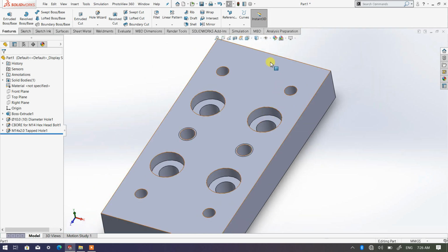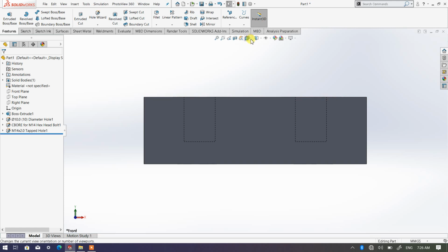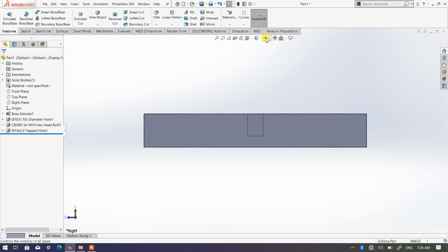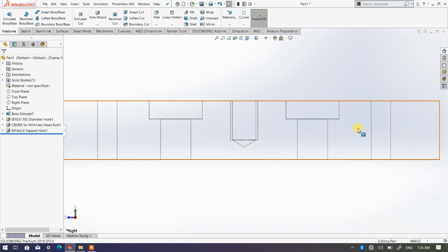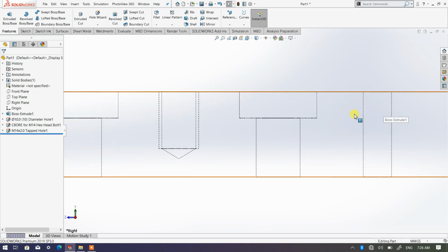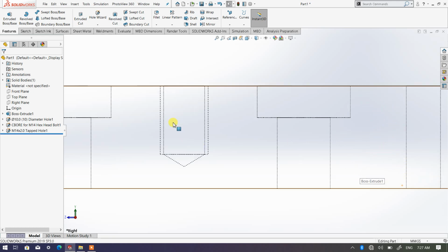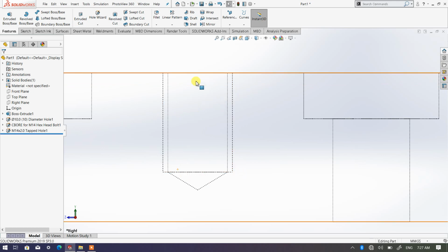All right. So if we pick the side view, let's make it right side view, and if we go to hidden lines visible, as you can see over here, this is how it looks like. All right, and this is through hole. Okay, as you can see over here, there's only one straight line here, one straight line here. Since this is a through hole without thread, and this is a hole with thread, if hole with thread, they do have two lines like this.